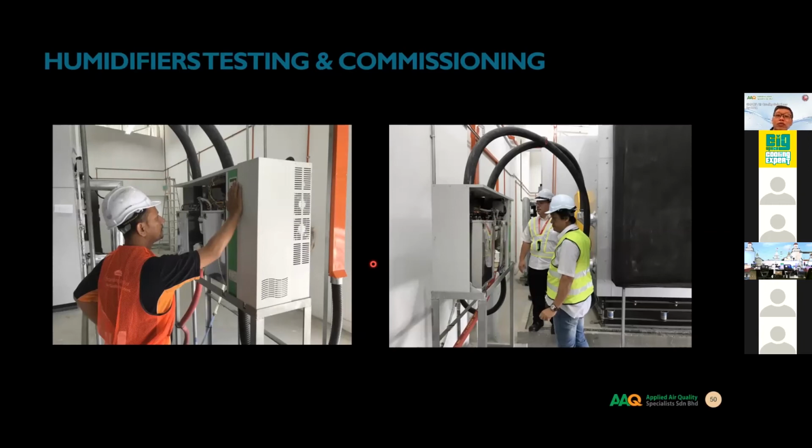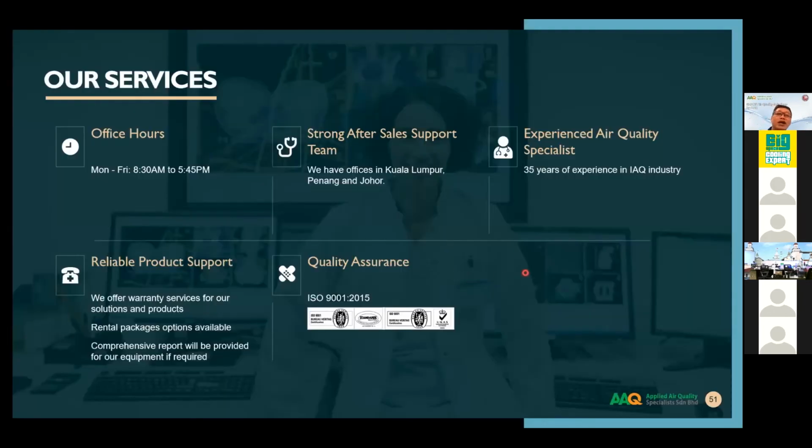The whole vehicle will be driven in, and the chamber is used to test conditions like cold temperature with high humidity, cold temperature with low humidity, high temperature with low humidity, and high temperature with a humid environment. Okay, I'm finished.